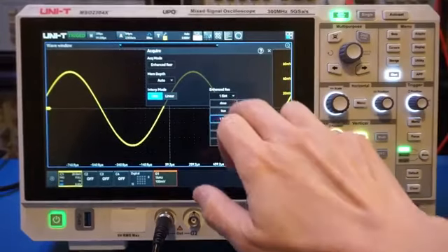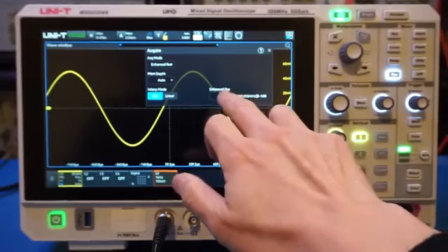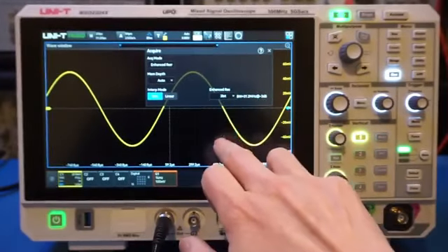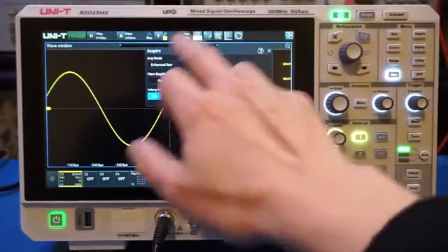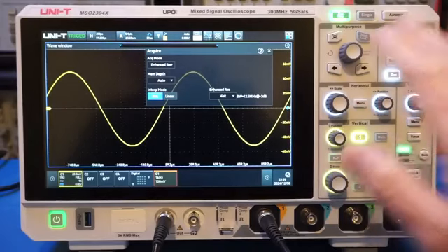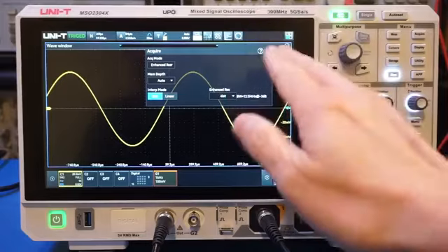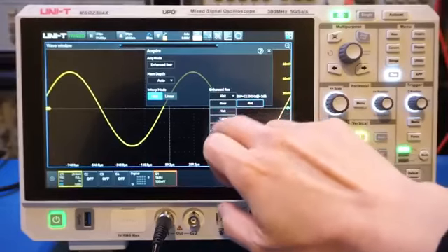Now, you can see here with 2 additional bits, the bandwidth now drops to 250 MHz. And with 2.5 bits, it further drops to 80 MHz. With 3 bits, it drops to 31.2 MHz. And with all 4 bits enabled, which is a 12 bit oscilloscope now, the bandwidth is only 12.5 MHz. So the drop-off becomes more drastic as you increase the number of bits of resolution. Definitely, there's a trade-off between the vertical resolution and available bandwidth. Higher vertical resolution is useful in situations where the signal being observed has high dynamic range. So let's change it back to the default.